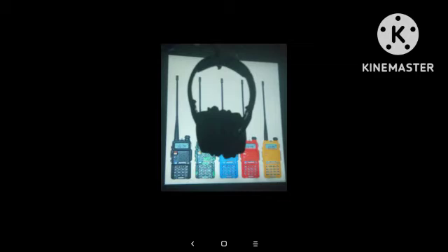3.5 meters or 11.5 feet. Number 31. The cubical quad or quad antenna consists of 2 or more square loops of wire. The driven element has approximately an overall length of 1 wavelength. Number 32. Moving the feed point of a multi-element quad antenna from a side parallel to the ground to a side perpendicular to the ground will have what effect? It will change the antenna polarization from horizontal to vertical.